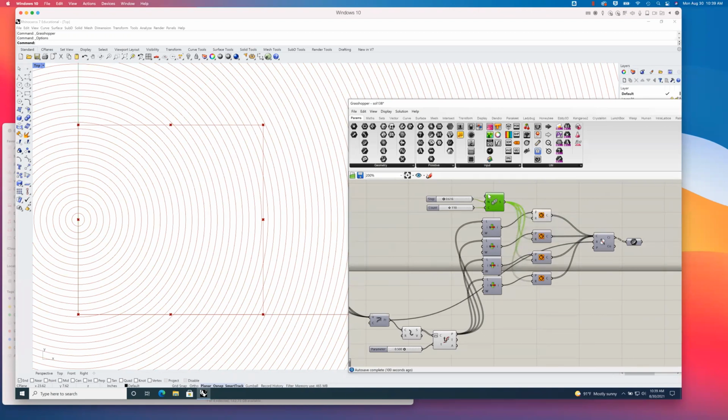So with a series, the way I make a list of numbers is I give it the first number, in this case 0. I tell it the step size for each successive number, and I tell it how many steps to perform. So in this case, I'm going to have 110 numbers, 0.616 units apart, starting at 0. So 0, and then 0.616, and then 1.232, and then 1.848, all the way 110 times till I get to 66.144. So what I did is I generated 110 values for the radius of a circle.